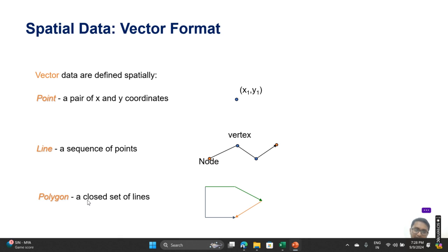Apart from that, when we talk about polygons, it is a combination of lines and points. So we have the latitude and longitude, then lines are also there, so we have lat-long information, perimeter, and then area, which is made by the closed geometry of that polygon. So here we have three different features: xy, then perimeter, and then area. When we talk about a point, we have just xy; for a line, xy and length of the road; and here xy, perimeter, and area. So four things it can represent.